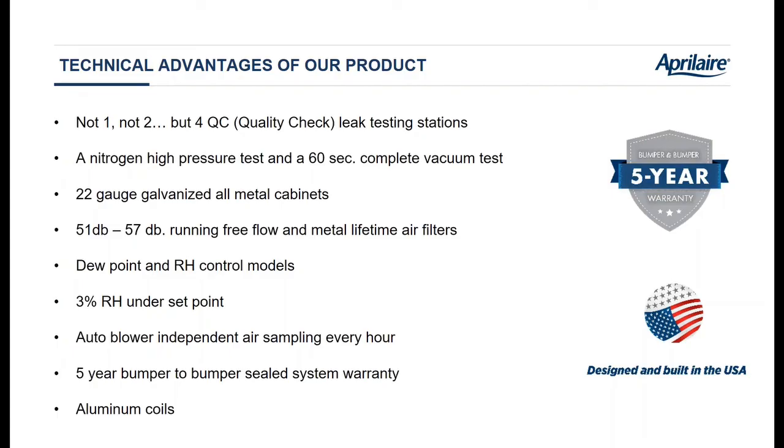Want to cover why would you buy an AprilAire dehumidifier instead of a portable? Start with the key of any AprilAire product, the quality controls, the quality assurance. We know when we ship this unit, it does not have a refrigerant leak. We pressurize it with nitrogen. We pressurize it with helium. The nitrogen catches larger leaks. The helium finds very, very small leaks. The helium molecule is far smaller than the 410A refrigerant. So if you can't sniff out any helium, you know you're not going to have a problem with refrigerant leaks right out of the box.